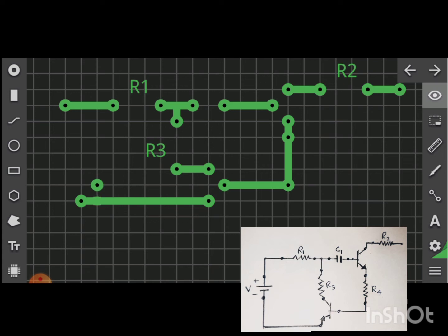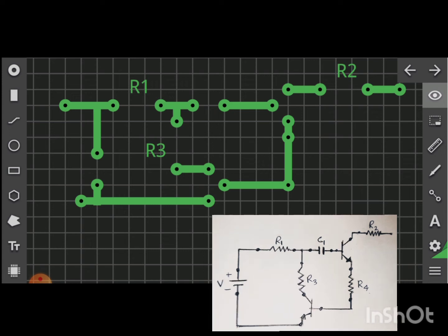You see, we can make a track like this for connecting the supply. Here we have so many points to connect: two points for the positive supply and two points for the negative supply. Not necessary, but if you could make it, you can. This is for plus of VCC, and you can mark a minus for the supply of the battery here. So we'll label the capacitor C1. I just increased the font size, and you can increase the size of the font as per your choice.